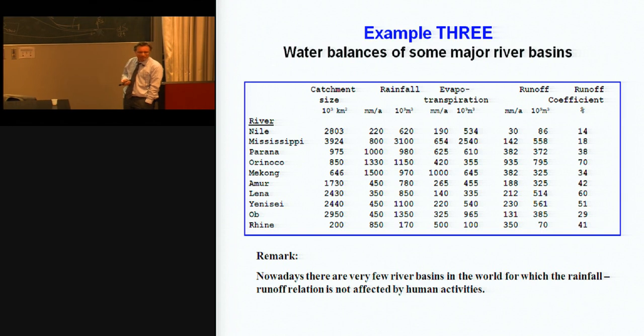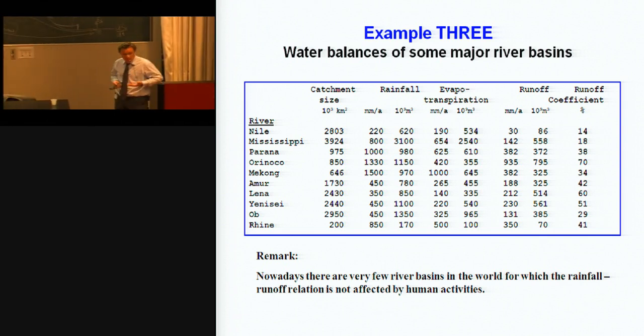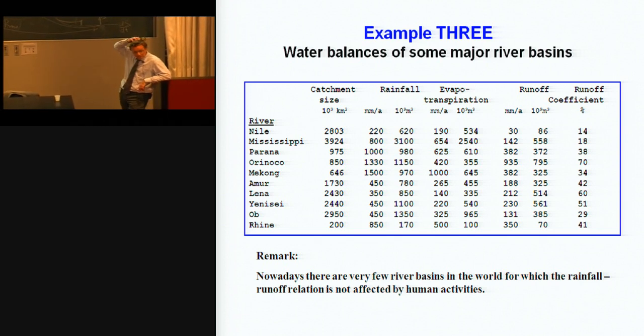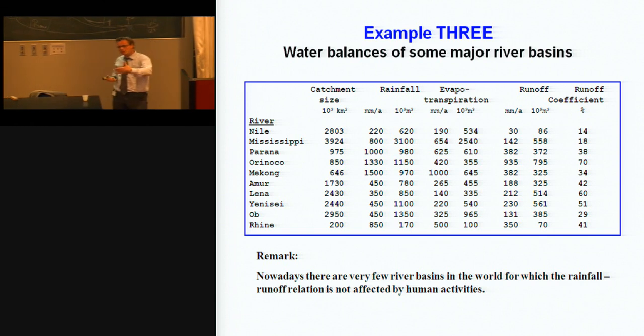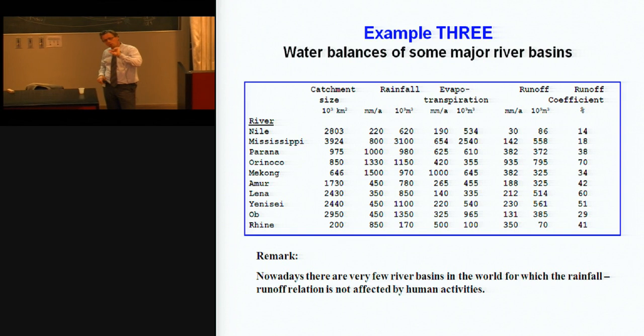Because it was measured in the rain gauges. Exactly. What do we measure in the rain gauge? A water volume in liters or cubic centimeters. Yeah. But how is that then transferred to millimeters? Divided by the area. If we have 1 square meter, a meter by a meter, and you have a water height of 1 millimeter, this is exactly 1 liter. So 1 liter per square meter equals 1 millimeter of rainfall. We divide by the area. It's very important.